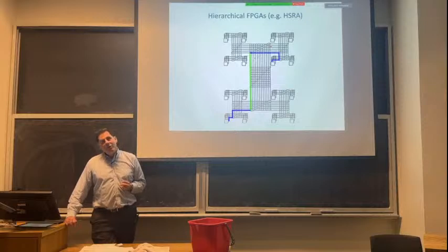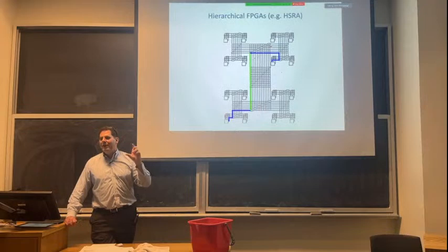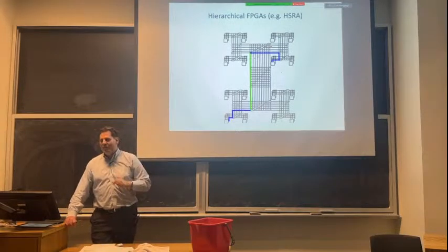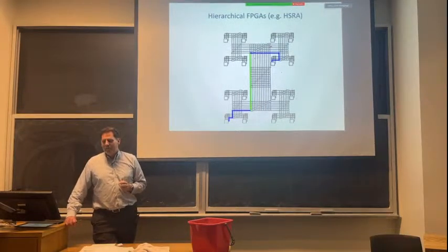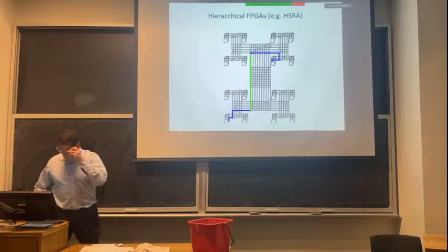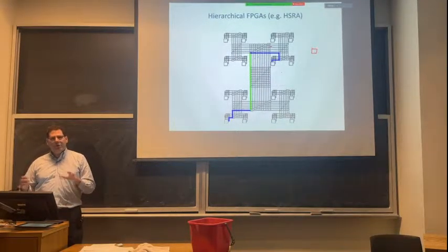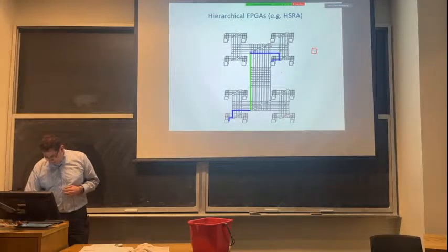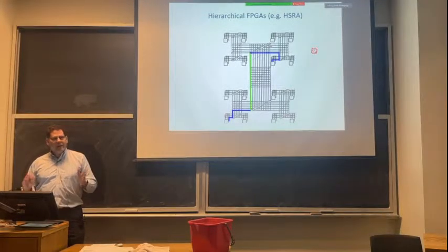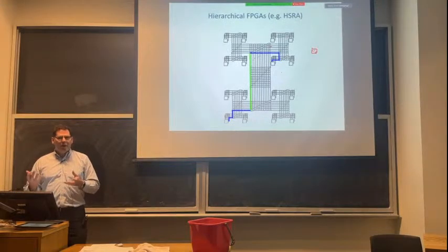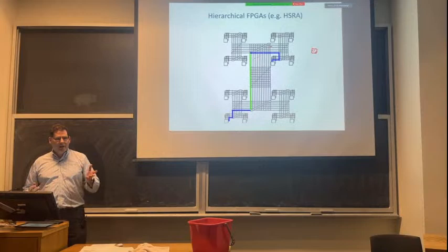It decreases for, well, what happens if it has to go all the way across the chip? So maybe this is too vague a question, okay? Did you say it's decreasing? Yeah, so maybe this is too vague a question. For short wires, what's happening as we scale our process technology is the wire cross-section is getting smaller, and it's actually getting quadratically smaller, which is driving resistance up. Resistance per unit length is actually going up quadratically, okay?